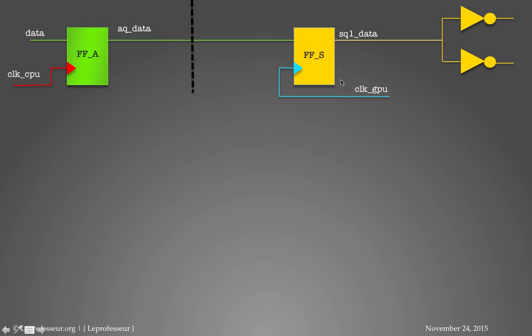Because of the inherent structure of flip-flops, the signal pulse width or toggling has to fulfill the criteria of setup time and hold time of flip-flops. If they don't fulfill the criteria, there is a tendency that this design will not work, simply because too many things are changing.